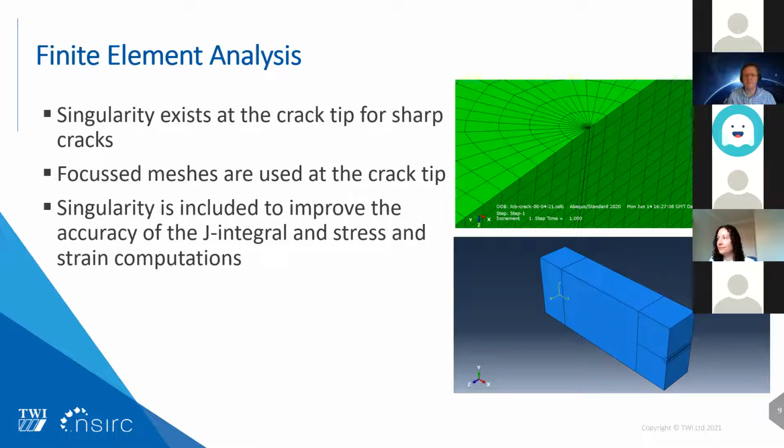As the stresses and strains at the crack tip are singular, modeling the singularity will require considerable mesh refinement near the crack tip. It has been shown that for 2D and 3D elements, the singularity at the crack tip is best described when the mid-side node is at the quarter point position.